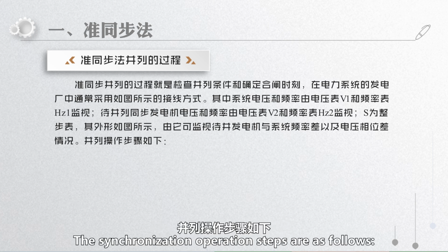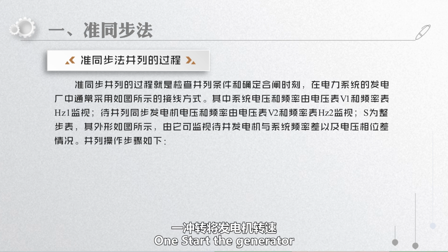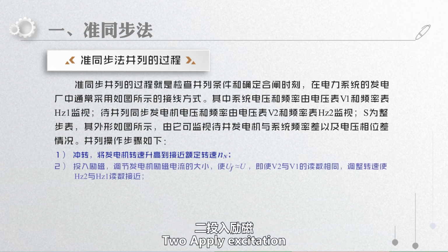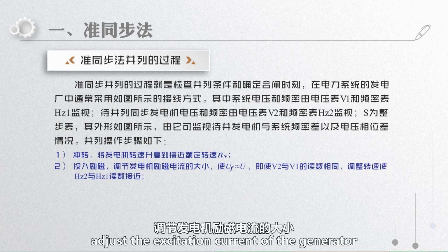The synchronization operation steps are as follows. 1. Start the generator and increase the speed to near rated speed. 2. Apply excitation.